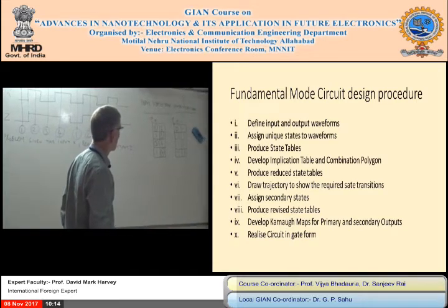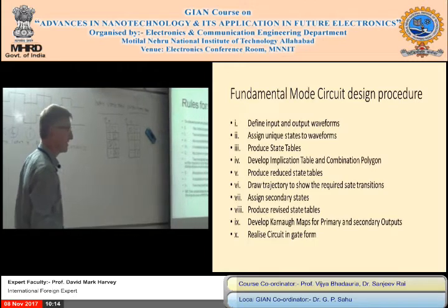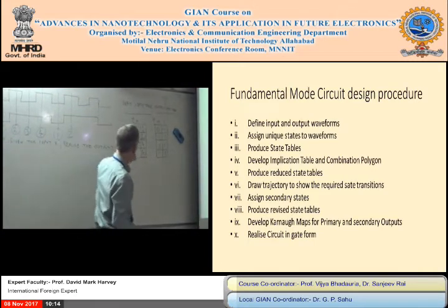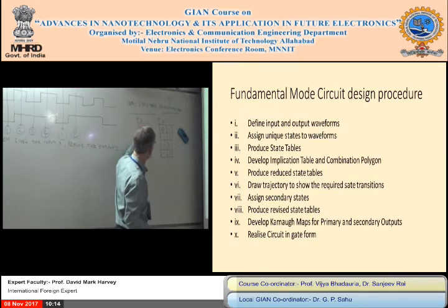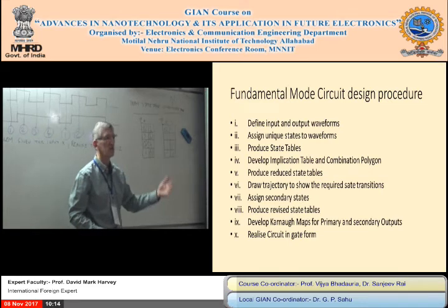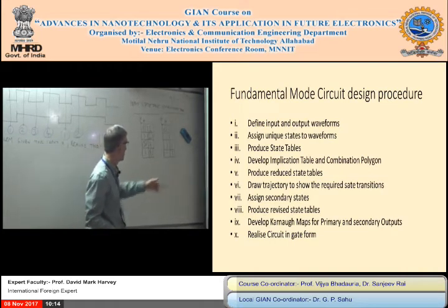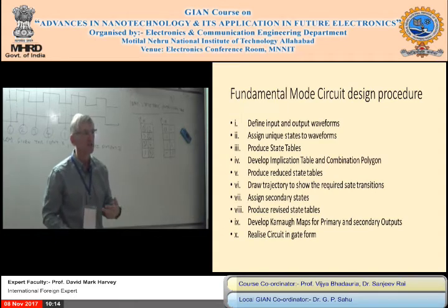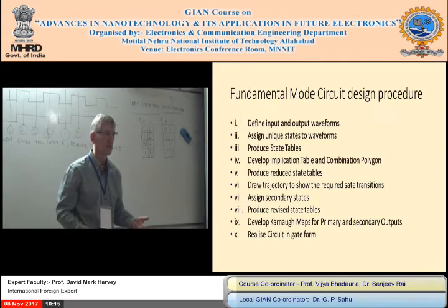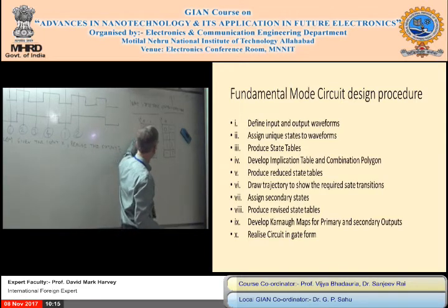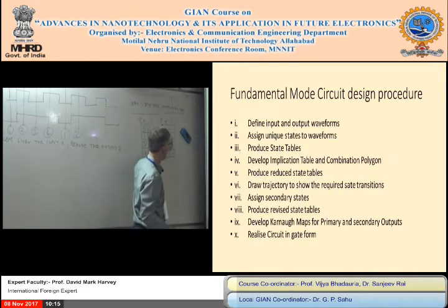Then the stable state with a transition state that are the same number. Well, this is what we did yesterday. Someone asked the question, if we were going to combine these 2 rows, for example, transition state 2 and stable state 2 are nearly the same anyway. It's moving towards that state. And even if the output changes, we can combine it, and the stable state output will override the don't care. So if you were to combine these two rows, 2 and transition state 2, the output will become a 1.